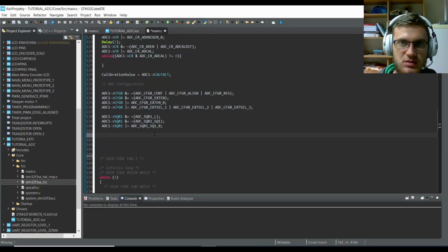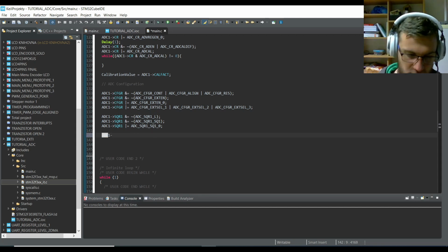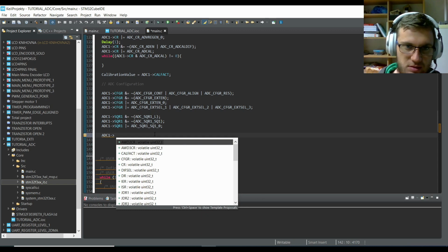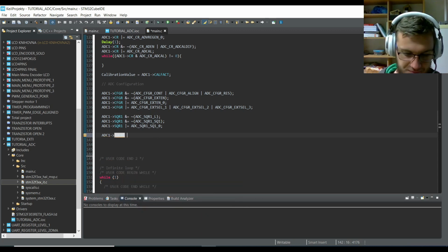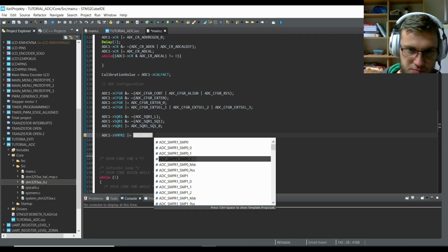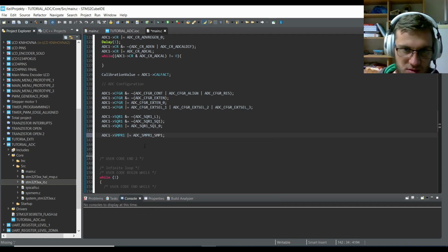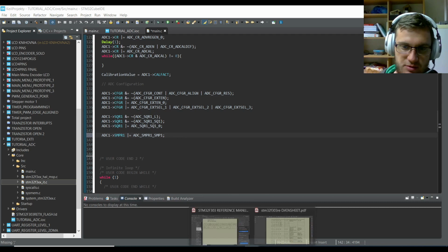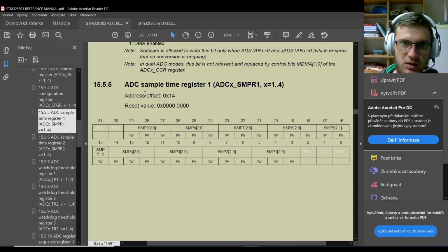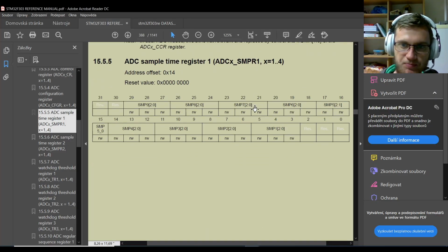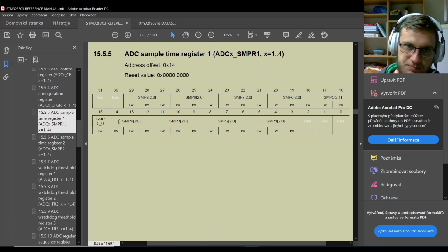Now let's set the sample rate. We already know that we want to use the slowest sample rate. I will write number 7 on position 3, and I will show you here in the reference manual. It is the ADC sample time register. You can see that for each channel we can set a different sample rate.